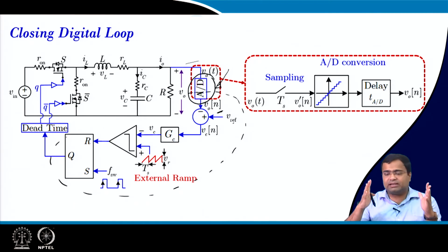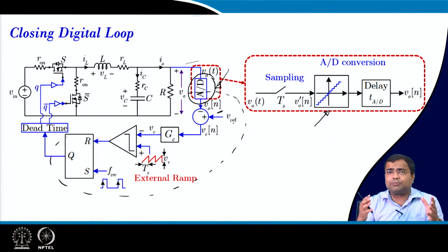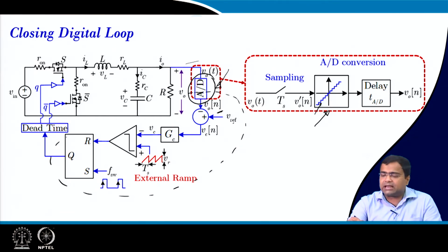The basic two things. In ADC, we have a sampler, as well as sample and hold, because ADC will also have a register. So, it will also hold, and also it will have finite resolution, because every ADC, whether it is 8 bit, 10 bit, 12 bit. So, depending upon the bit size, the resolution of this staircase will actually change. So, with higher resolution, this staircase will slowly become like a straight line. So, the size of this step will be reduced if you increase the bit size.